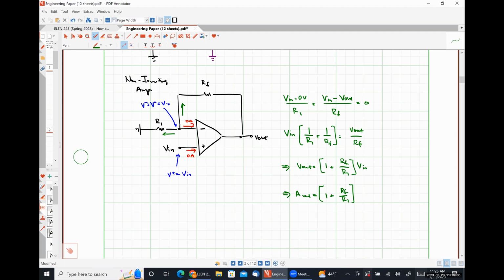So effectively, if we have a source connected to our input that isn't capable of driving a large amount of current, something like a piezoelectric crystal, that's really good at creating voltages and pretty terrible at making currents that go along with it, we can run that output signal from our piezoelectric crystal, which is part of some sensor, through an op amp to provide us a good output signal without worrying about the need to drive some load or something like that.